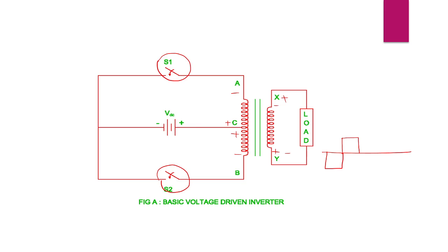So the basic inverter circuit consists of two switching devices. Alternately switching S1 and S2 on and off, the output voltage is available at the output. This voltage is later converted into a sine waveform, but it is available in the form of a rectangular or square waveform.